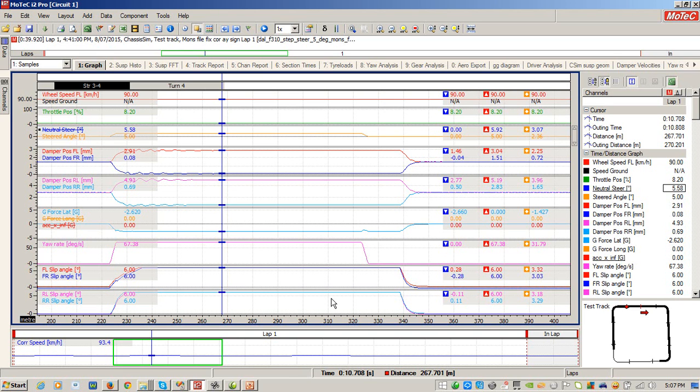Where this is absolutely screaming for, if you're an OEM watching this, it's a brilliant tool to investigate what the car's going to do with a step steer or with a chicane replay situation. If you're involved in Formula SAE or Formula Student, this is a great little tool: you can put in a rough tire model, put in a setup, give it a step steer response and start to get an idea of what it's actually doing.